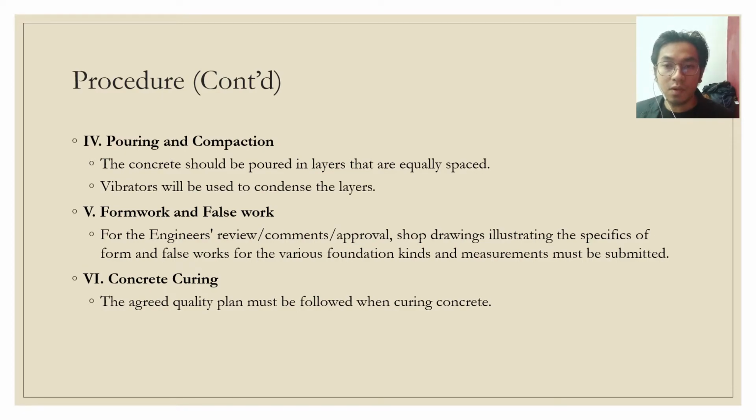The fifth is formwork and false work. For the engineer's review, comment and approval, shop drawings illustrating the specifics of form and false work for the various foundation kinds and measurements must be submitted. Lastly is the concrete curing. The agreed quality plan must be followed when curing the concrete.